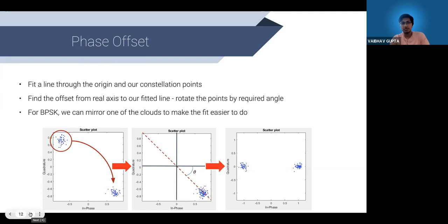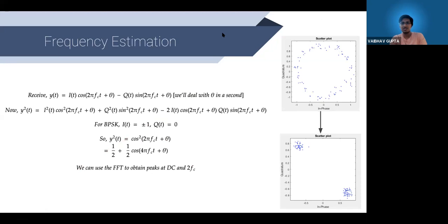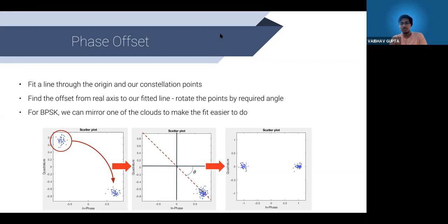So once you've corrected for the rotating fc and for the phase offset, you get a scatter plot that has some amount of noise that is inherent to just communicating over air. But this is still something we can deal with. If we define our boundary at 0, as we did in the previous assignment, we can see that I can pretty reasonably guess everywhere where I transmitted a 0 and everywhere where I transmitted a 1. So from something where I had just about no idea what was happening, I can now say with reasonable certainty that I've transmitted a 0 or a 1.